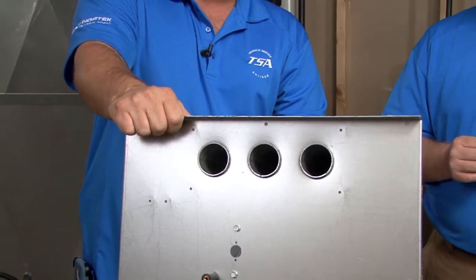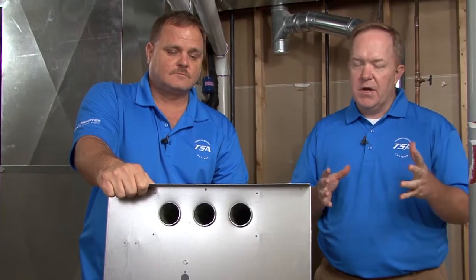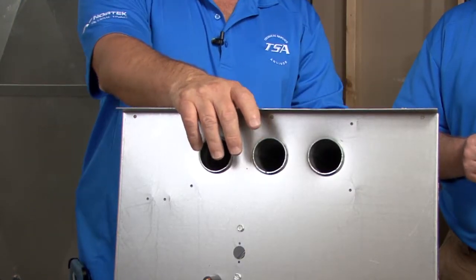Rollout shouldn't automatically send you into a mindset of, I must obviously be looking at a heat exchanger problem here. Even if you were to perform a smoke test as an example, and the results seem not to be as definitive as what you had hoped, we will always want you to err on the side of safety. So if you prefer multiple methods, we're not going to say that those don't qualify, or that we won't want to listen to what you have to say or what types of evidence you're collecting, regardless of the method you're using.